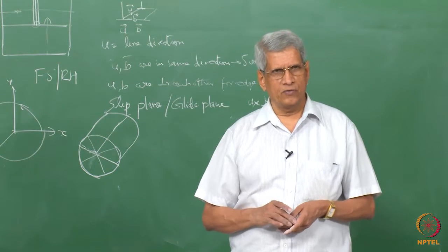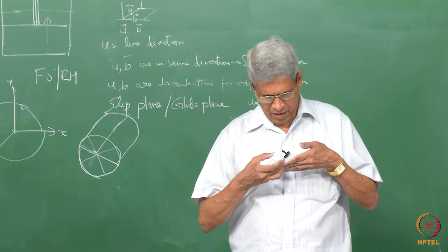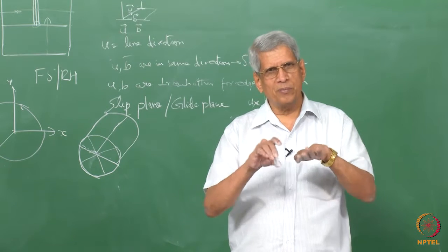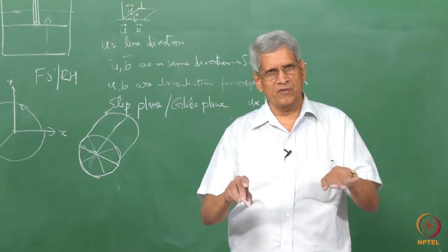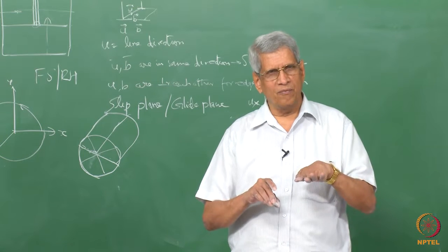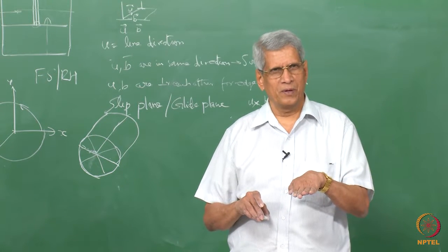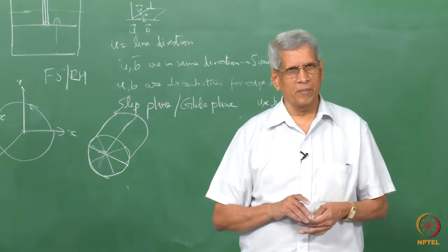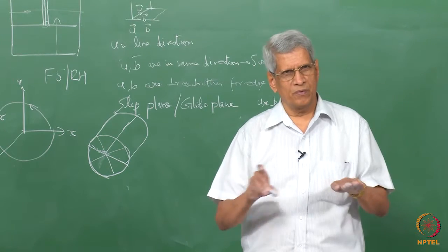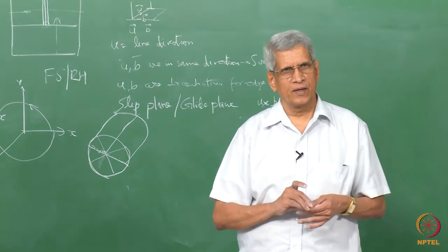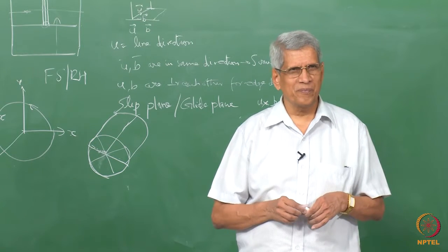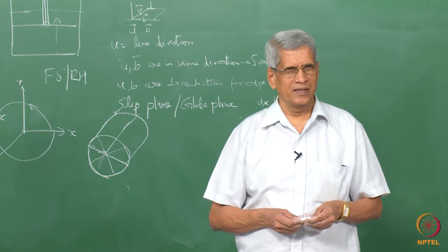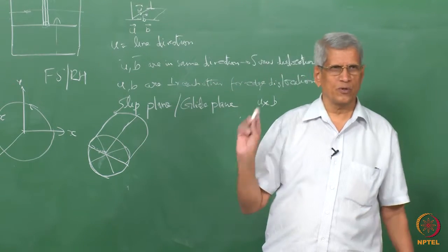It is something like this. If you are riding a cycle on a road, and the road is quite bumpy because lots of big stones have been put there, then a lot of energy is required to go on that road. On a smooth road, with the same energy you can go very easily. So that's the one which you would prefer to go. Exactly like that, the dislocation also chooses the plane which requires less energy to move. Those are the ones chosen as the slip plane.